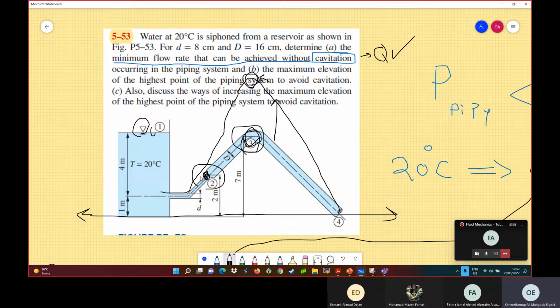We remember from our calculation, we found that with this configuration, the point 2 is the critical point where the pressure will be the minimal. But now assume that I'm rising this point to a distance h until this point becomes the point where cavitation will occur. And you are applying the same volumetric flow rate that was causing cavitation here. Okay, it's not causing cavitation, it's about to cause cavitation. And now this is your variable till where you can raise this point, because when you raise it, the pressure will keep dropping until you have cavitation. So what's this height?